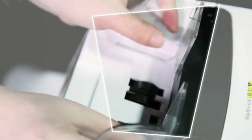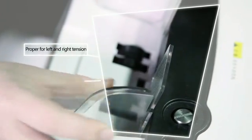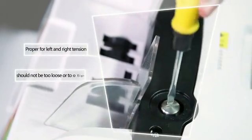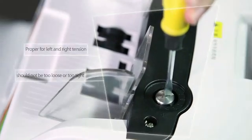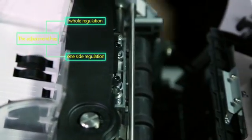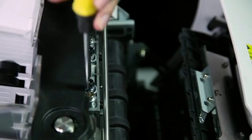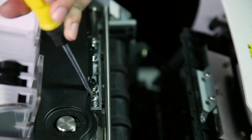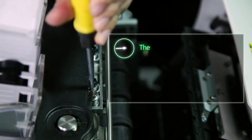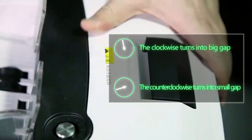Adjusting the gap of feeding. The gap of feeding should be proper for left and right tension. It should not be too loose or too tight. The adjustment has a hole regulation and one side regulation. Use a slotted screwdriver or one coin to slowly rotate the knob on the top right side of the machine. Clockwise turns into a big gap. Counterclockwise turns into a small gap.